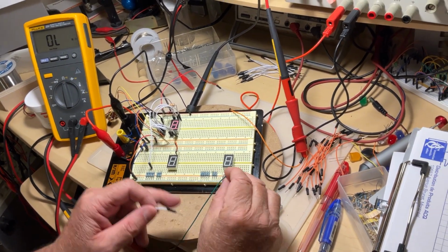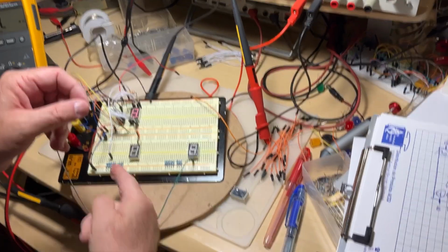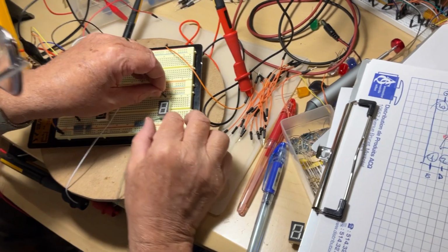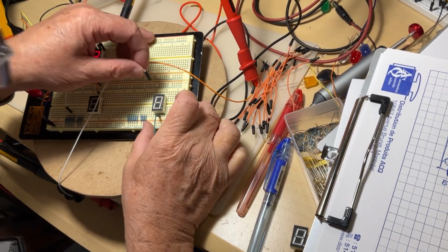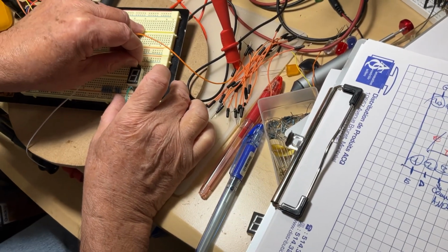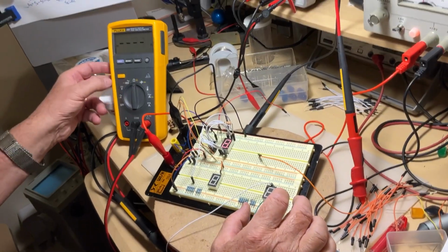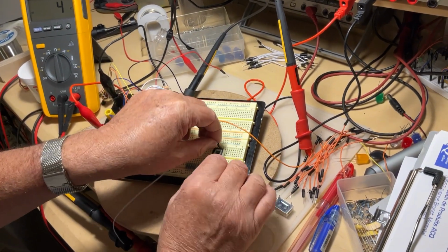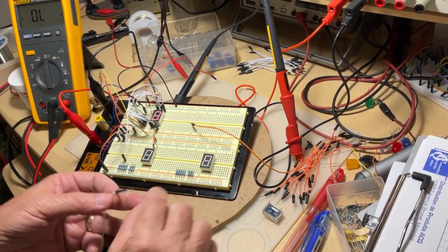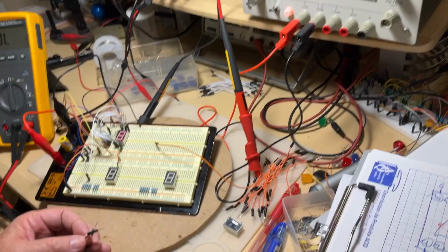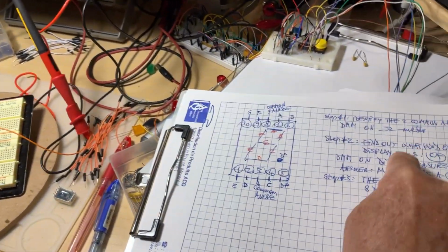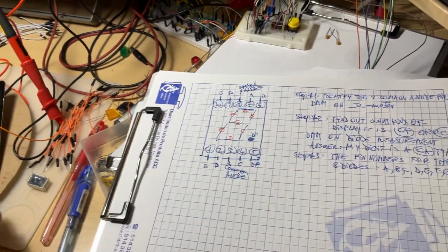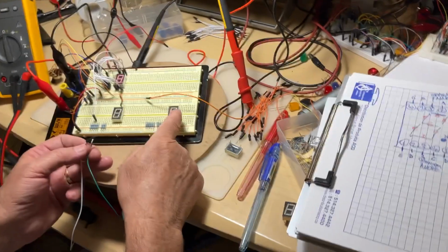And I go directly to see if the pins 3 and 8 are together, because I identified it already on the other one. Okay, so let me see. Yes, pin 3 and 8 are connected together, exactly like for the other one. Now, step number 2. What kind of display is it? Is this a common anode like this one, or is the common cathode?